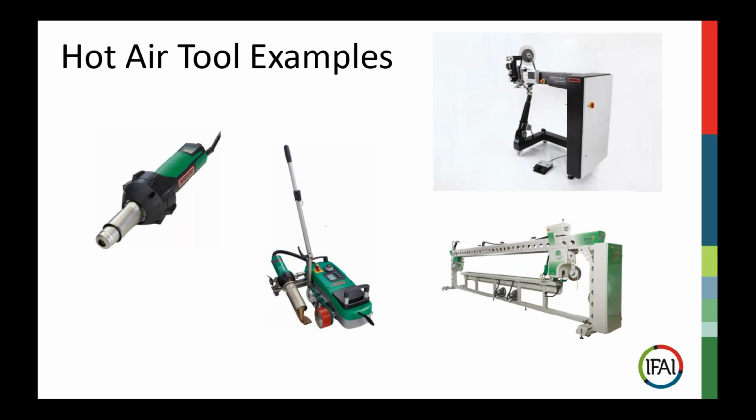The next level up after an automatic welder would be a stationary welder located in the top right. Very similar to a sewing machine, the welder allows you to weld continuously. So you can weld on this machine 3D welds, which we'll talk about a lot with hot air welding because it's one type of equipment that allows you to do these curves, do drop stitch, do inflatables, do kayaks, rafts, anything you can think of where it's not just a straight line weld. You can really get into intricate, detailed work with these stationary welders.